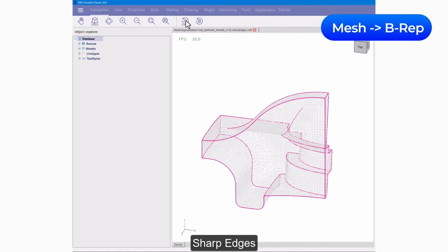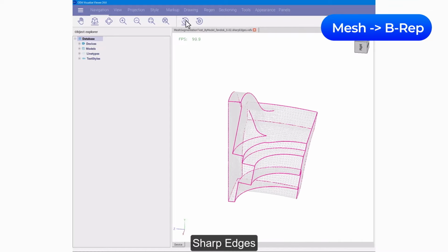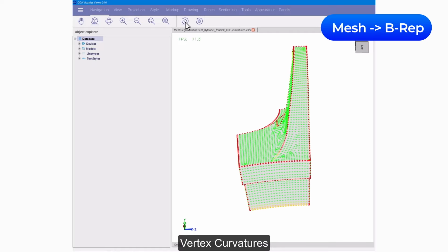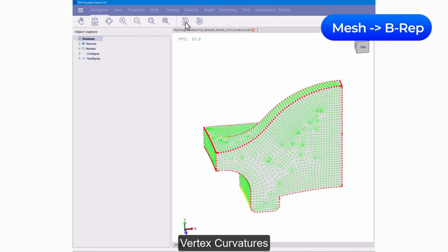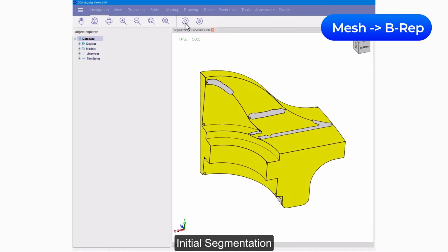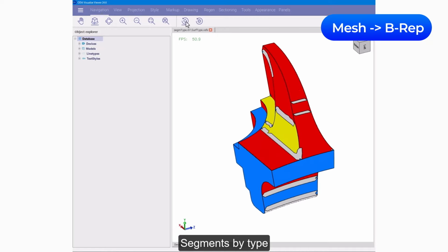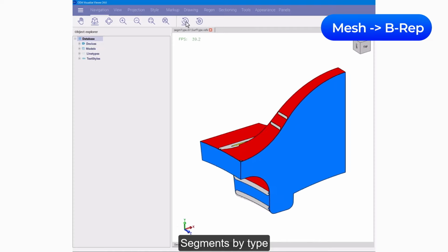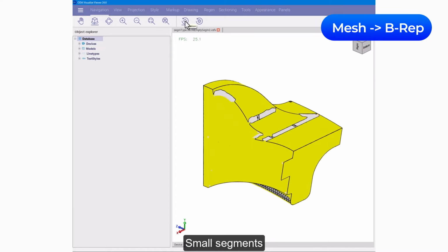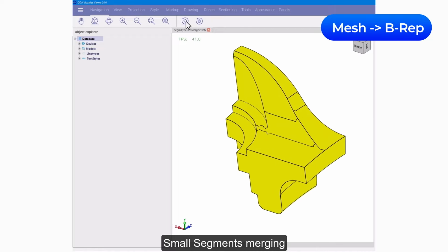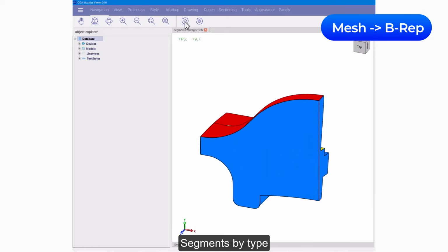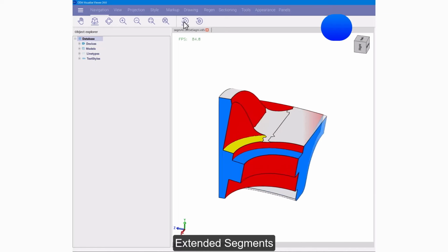Here we have implemented a quite complex workflow which allows us to recognize canonical surfaces: planes, spheres, and cylinders. This workflow includes many tasks, like detection of sharp edges, calculation of curvatures, segmentation of the initial point cloud, spatial extraction of planar and cylindrical segments, and finally, recognition of the canonical surfaces. The work we have already done gives us the opportunity to start the next important task, creating BREPs based on the intersection of canonical surfaces.